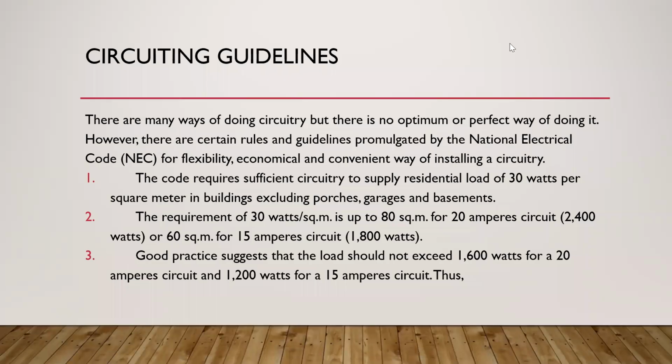Number two guideline, the requirement of 30 watts per square meter is up to 80 square meter for 20 ampere circuit or 60 square meter for 15 ampere circuit. Number three, a good practice suggests that the load should not exceed 1,600 watts for the 20 ampere circuit and 1,200 watts for 15 ampere circuit. So again, mali yung pagkabasa ko.